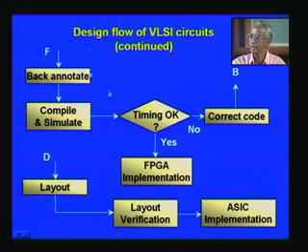So once you have given a particular, you can, in the beginning stages, go about freezing even the hardware, saying that for the FPGA, these are all the IO pins, these are all the clock signals, and based on that information, PCB work could have started right from day one when you started the Verilog coding. That means hardware and software design go hand in glove, and you have to interact with each other. Normally a team of engineers will be allocated for the hardware design, and another team for the software coding, say this Verilog coding, and you have to interact with each other and get the final product.